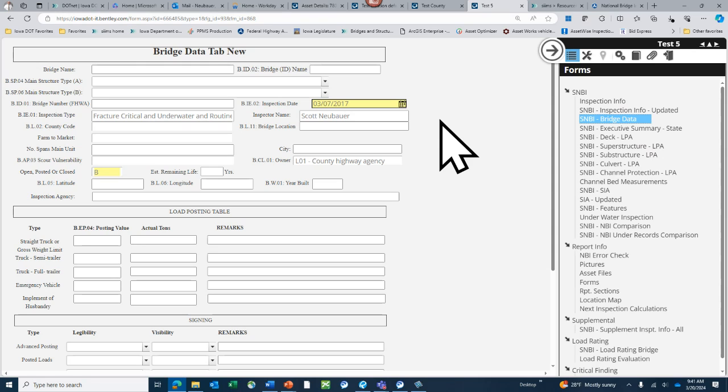But to offset that, they never had a requirement that forced us to go to 12 months in the past. They would recommend going to shorter frequencies, but now they have criteria that says you have to go to 12 months when certain things are met. Because of that, we're going to have more bridges on 12-month frequency than we had in the past. Not every county may see this, but in general, you'll have more bridges go on 48 than go on 12-month.